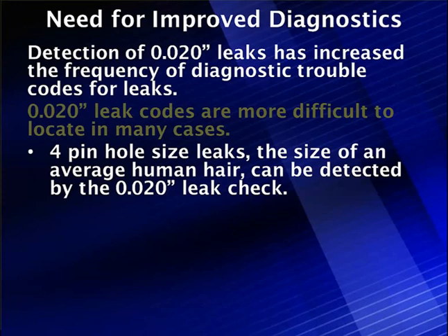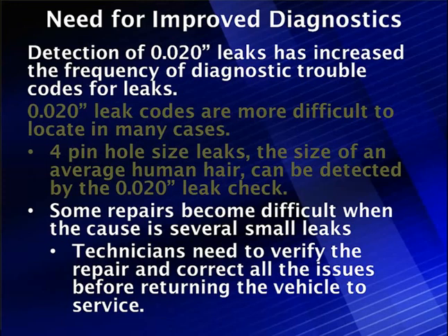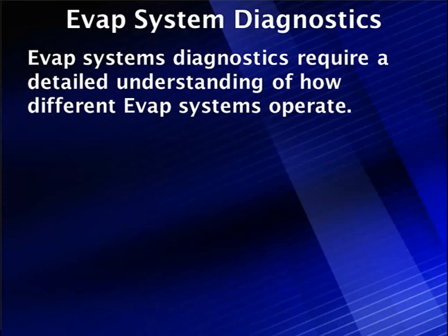Will one pinhole do it? Good question. Will two? Probably, but you need to measure that. We're going to talk about that. Some repairs become difficult when the leak is caused by several small things. You need to verify the repair and correct all of the issues before returning the vehicle to service. We're going to talk more about that, but they require detailed understanding of how the different Evap systems work and what you're going to be seeing.